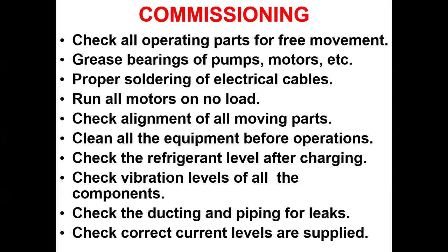Okay, now. Then check the refrigerant level after charging, check vibrations, then check the ducting and piping for leaks. Then, once again, you need to properly supply the current levels. Otherwise, the entire board can be blown off. I told you the VRF board costs around 1 lakh something.